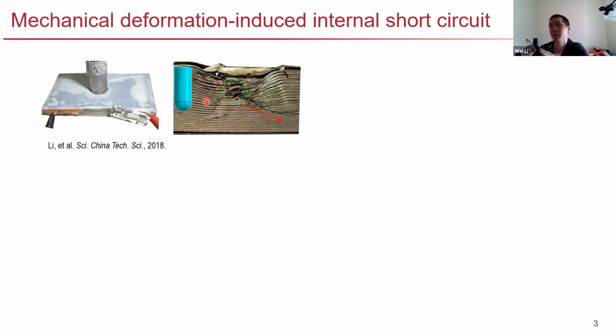They are basically the anodes, separators, and cathodes. And then we can see 2 kinds of fracture patterns. One is the very localized fracture under the indenter, and also somewhere far away from the indenter, we can see a through thickness shear fracture. So these are basically the 2 different fracture patterns.